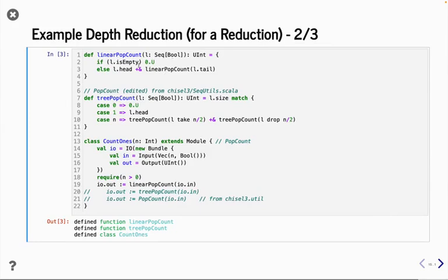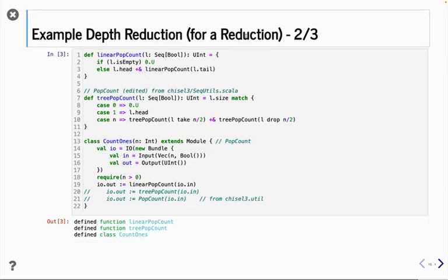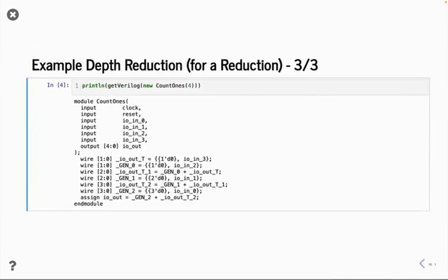So you need to grow the result sum to handle that information. That's why we're using the non-truncating addition. This is the growing addition. And so in the Verilog, it's initially growing the inputs before it starts adding on to things. But the key thing is there are 3 additions in sequence.